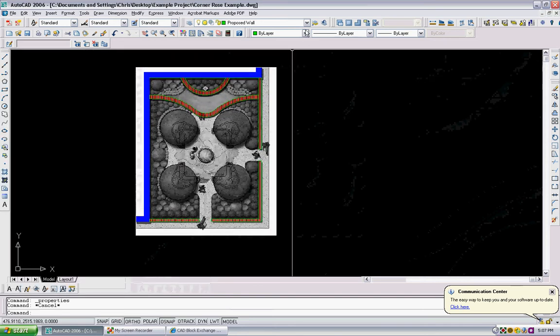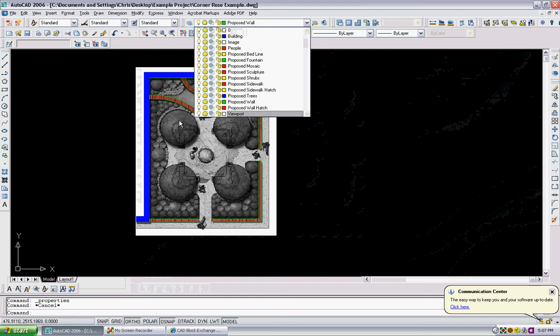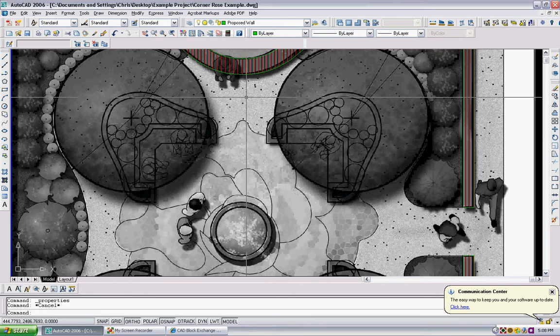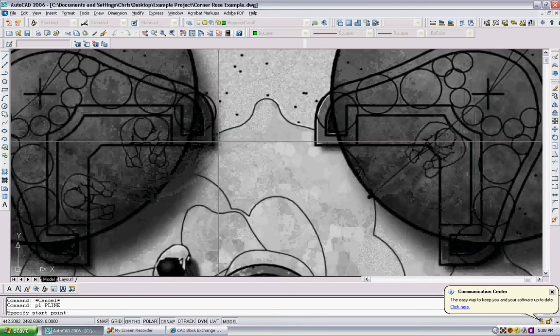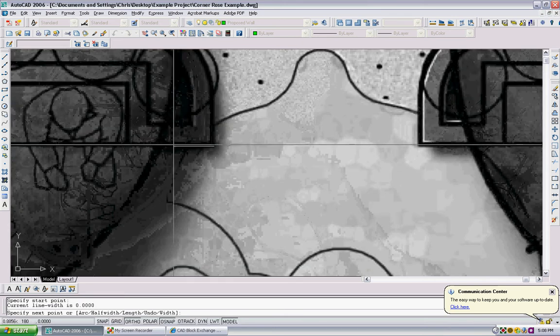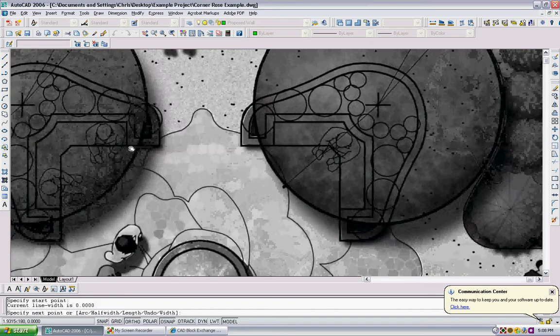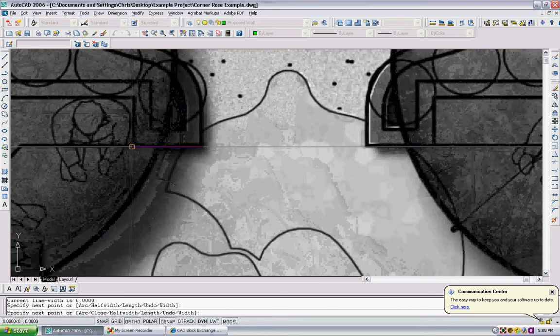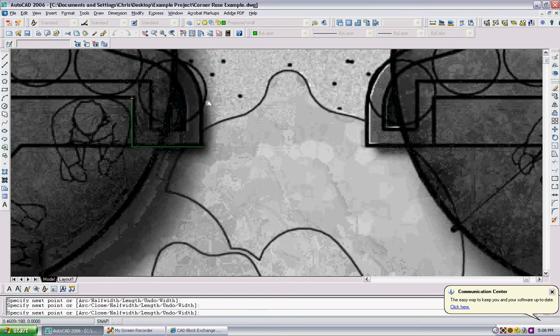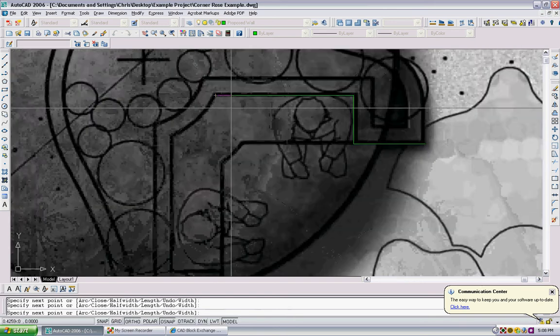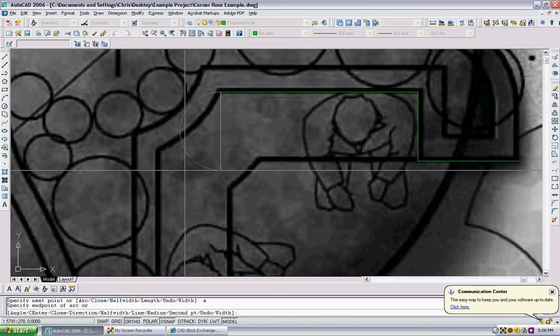Now let's make one of these planter bed seating nooks. I guess it's plural, it's more than one. Where am I at? Let's go back to the... I guess I did it in the wall layer before. Okay, so I'm on my wall layer, and I'm just going to kind of bang this guy out right here. So bang, and I'll do the seating second. Come on, I got my ortho on right now to keep my line straight. Get here and A, enter, turn the ortho off.